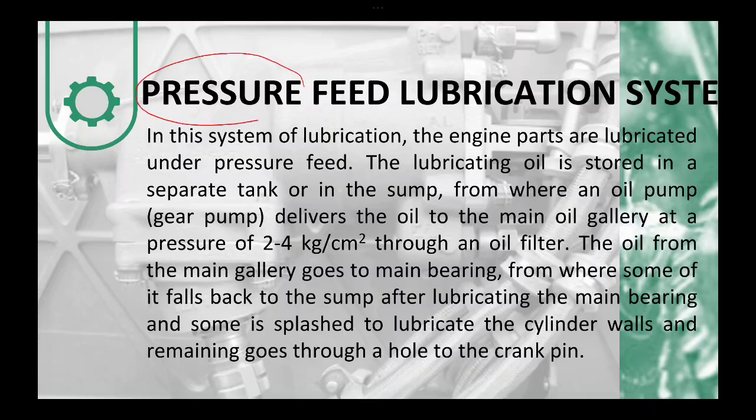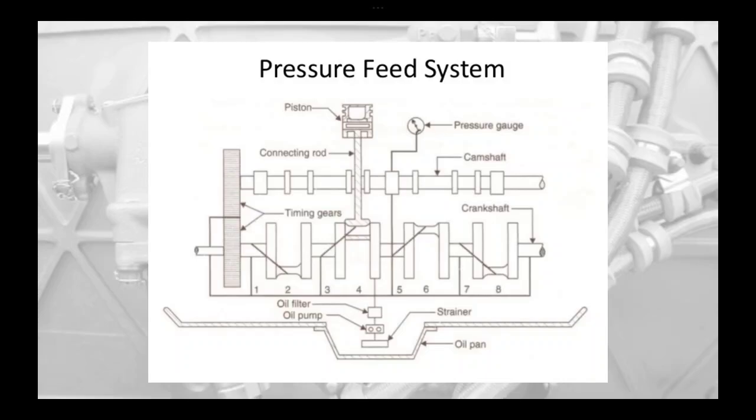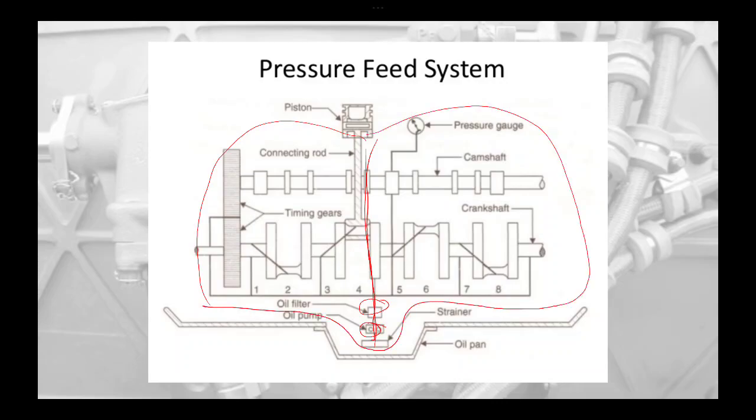So from the word pressure, there's a pressure on your system. Okay, you do have your oil pumps. That's pressure. It works just like this one, so this is your oil filter and oil pump. The pressure will be taking that oil, then splash it onto the upper system. Then the excess oils will go onto the oil pan. And that's how pressure feed works.